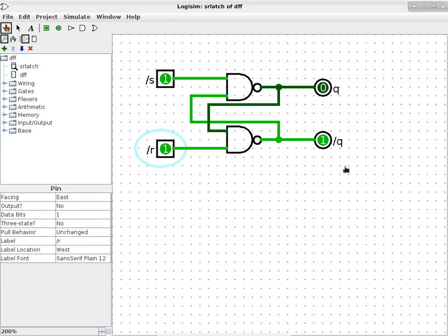So I'm guessing there's no actual hardware way of fixing it other than to make it asymmetrical. To fix this, you basically have to make sure that you do not have a scenario where both inputs go from 0s to 1s at the same time. So you have to fix the source of the issue and not the symptom. There are ways to make sure that you cannot have both inputs going from 0 to 1s at the same time. The thing about the SR latch is it usually is not used by itself. It serves as a component in larger memory devices. So when you design the larger memory devices, you have additional circuitry to make sure that does not happen.